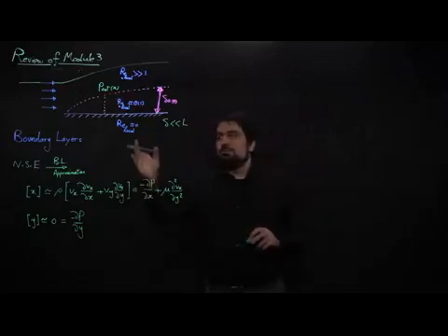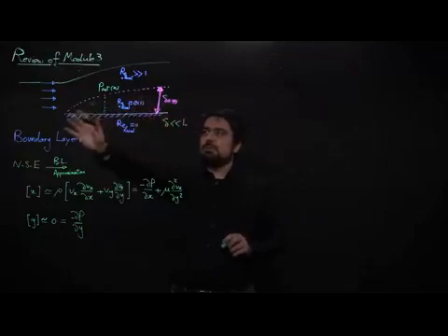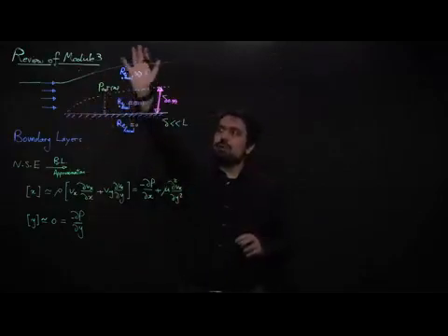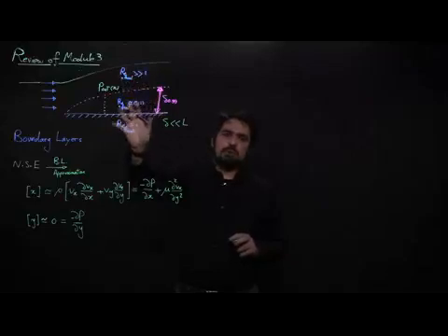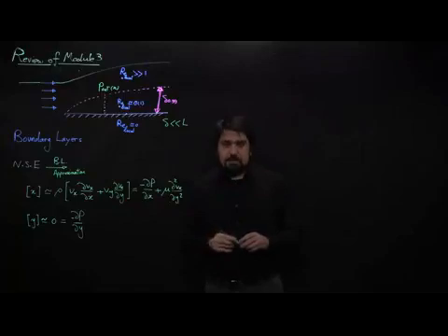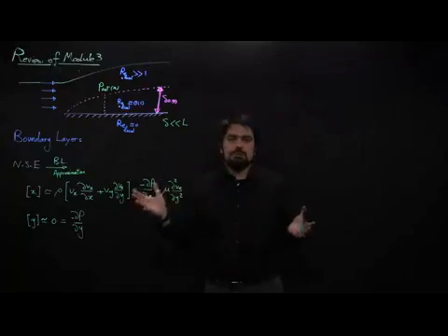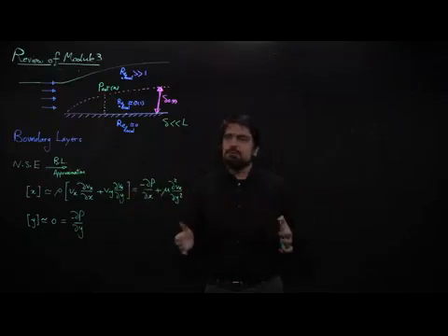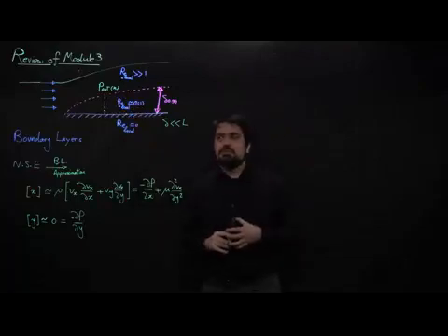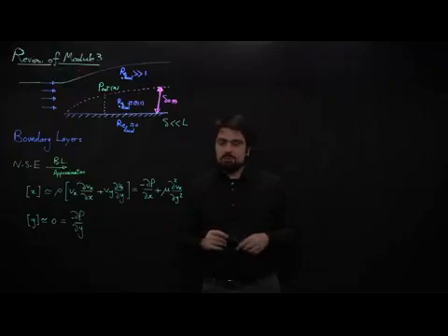And this fact that pressure inside the boundary layer is imposed by the outer flow is how the solution from the outer flow speaks or communicates with the solution inside the boundary layer. And at the end of the day, our problem comes down to solving these two different regions together and making sure that they are talking with each other through the pressure. And the fact that the pressure field inside the boundary layer is set by the pressure field in the outer flow enables us to do that.